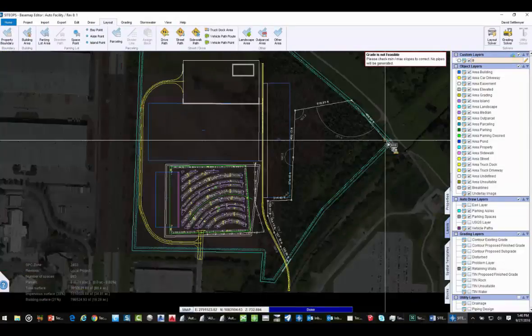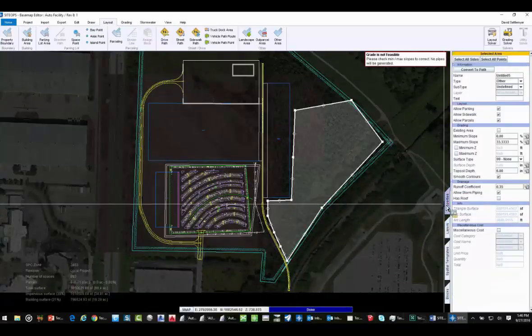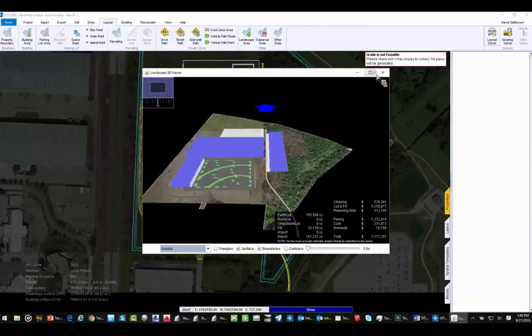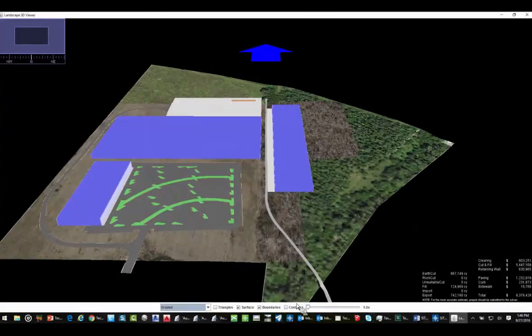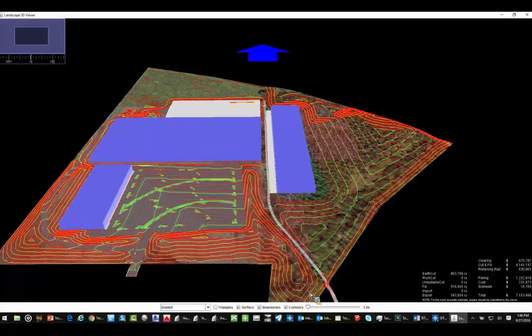I'd come out and identify an area, and I've got one of two things I can do. I can tell SITEOPS this is existing, and it doesn't do any cut at all. Or I can tell it, let's do a 10% grade. Or I can use grading constraint slopes if I want to actually do some grading out there, but not a lot. Once we go out into this area, I'm still allowing it to fill. It's just not making these crazy hills as we go forward. It's more of a controlled fill. And now you see it's actually going out,